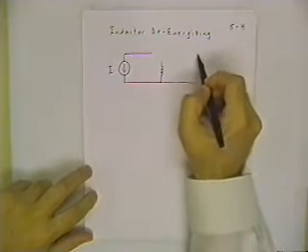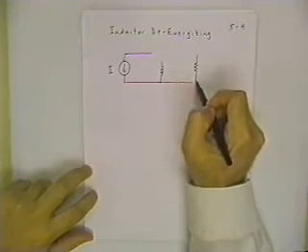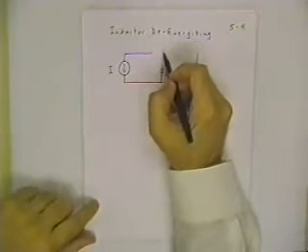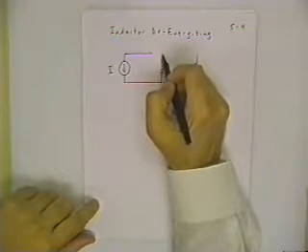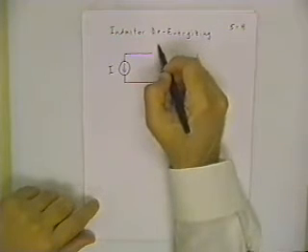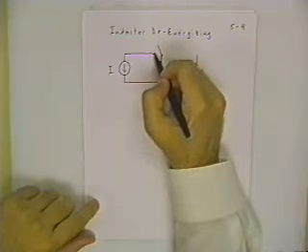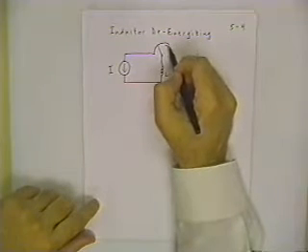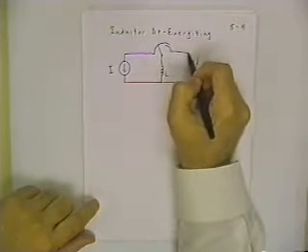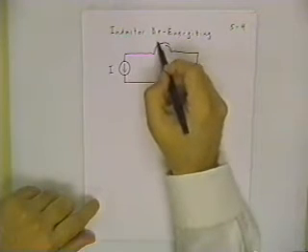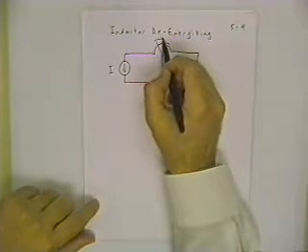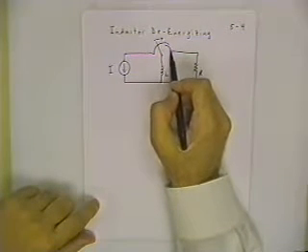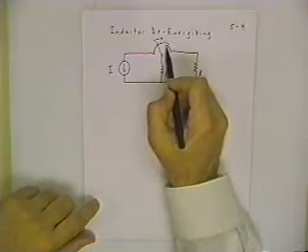Okay, and then we have a resistor over here. And what I need to arrange for here, and there's a practical reason for this, I need a switch that's going to smoothly switch from connected to the source to being connected to the resistor. And so I'm going to use a switch that kind of looks funny. It's supposed to indicate that here is the moving element of the switch, and as the switch slides over from this position to this position, there's a continuous contact.